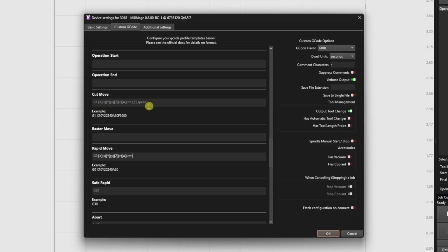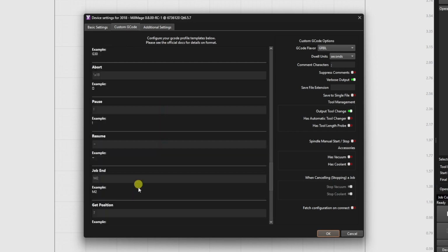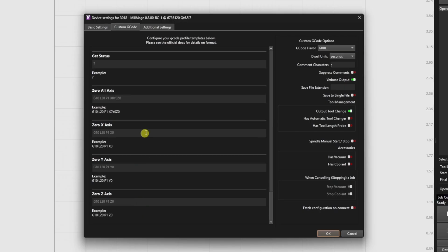And you have it for all of these axes. So it will only emit the things that are necessary. The curly braces are where you have to put variables, and the square brackets are just telling it that it's optional. You can remove the square brackets if you always want to emit everything. And then there's a bunch of other examples in here. So this is extremely and highly configurable. You can manage as much as you want or not in there. In general, these should just work for the flavors that we've provided, but you can customize them all that you want for your specific machine.